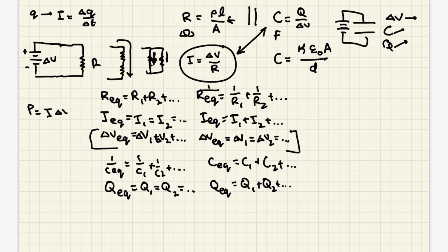And so the main formula is I times the potential difference. The current going through a specific light bulb, or to be honest, the current going through anything times the potential difference going through that thing. And you can modify this using Ohm's law and basically write as I squared R or delta V squared over R. And it's going to be the same thing. You can just plug in different values using Ohm's law and you're going to get the same exact equation. They each have their different purposes.